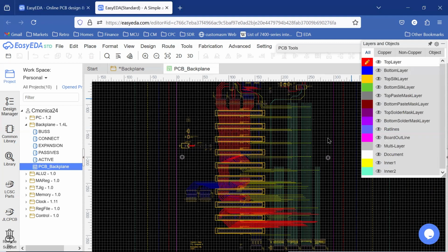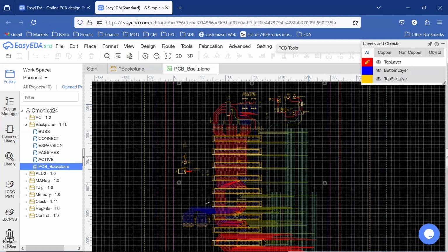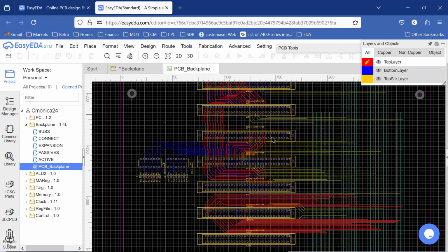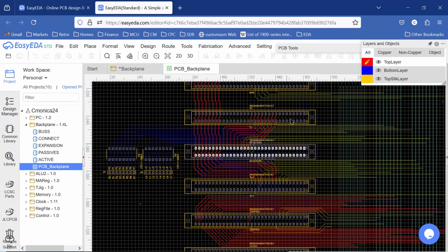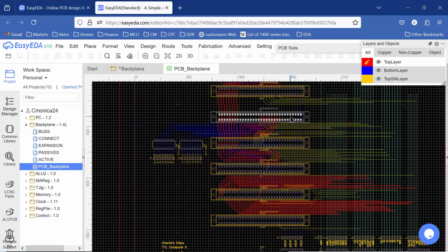So when I was fleshing out the card design, first thing I did obviously was have the card edge connectors in place. I knew where the issues were, right? I knew where a lot of the signal crossovers between cards was going to occur. So I did that first just to see that I was okay with doing the routing. I went forward with that to a certain level, and got to a point where I was satisfied that I wasn't going to paint myself into a corner, and then would go on to doing the routing in a different area.